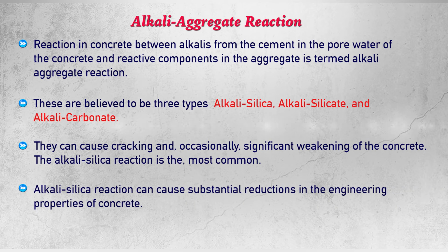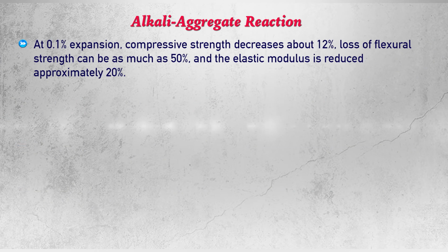Alkali silica reaction can cause substantial reductions in the engineering properties of concrete. For example, at 0.1% expansion, compressive strength decreases about 12%. Loss of flexural strength can be about 50%, and the elastic modulus is reduced approximately by 20%.